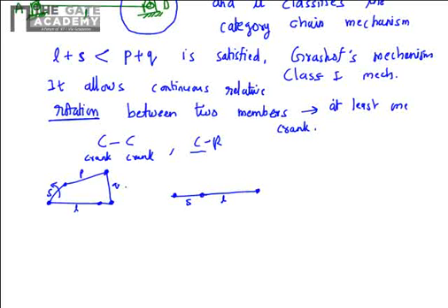At that time, if the shortest link were to have a complete rotation from this angle of -180 degrees, then the links P and Q should allow it to come to this position of angle 180 degrees. If the lengths of the links P and Q were shorter, then S would have stuck somewhere at some angular position, and this is the case where Grashof's condition is not satisfied.